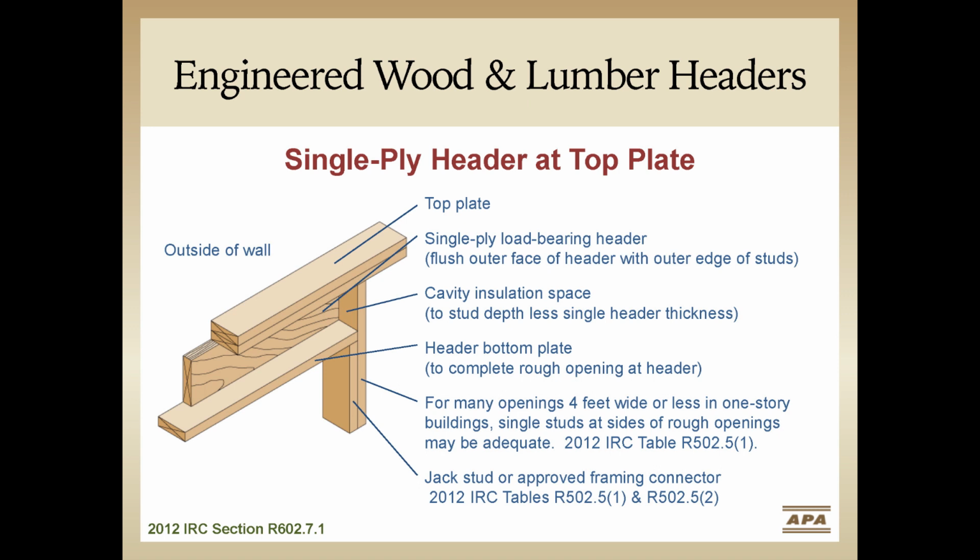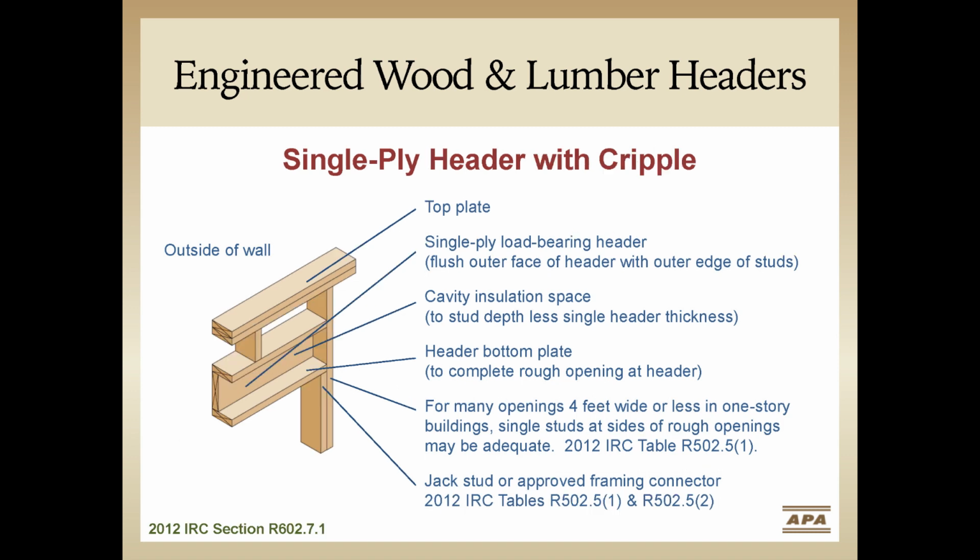And there are also some proprietary products that are likely available in your market that are pre-insulated, so check with your local suppliers for their availability. Single headers can be placed at the top plate, as shown here, or at the head of the opening, as seen here. This header has a short wall framed above it to accommodate the geometry of the design.